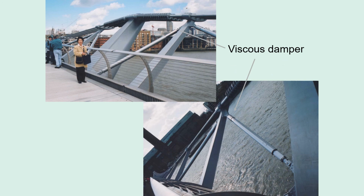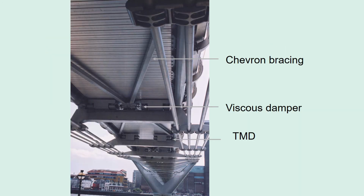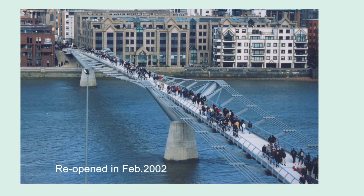These viscous dampers were installed on the deck. Under the deck, chevron bracings, viscous dampers, and tuned mass dampers (TMD) were also installed. The vibration was successfully suppressed, and the bridge was reopened in 1.5 years' time.